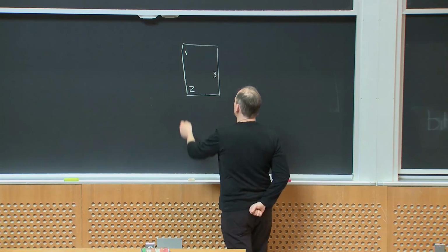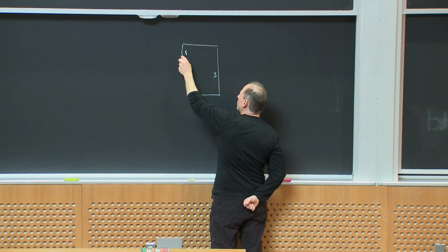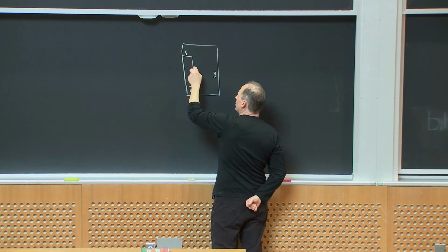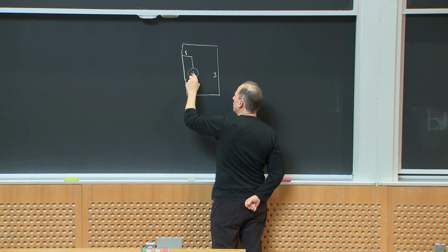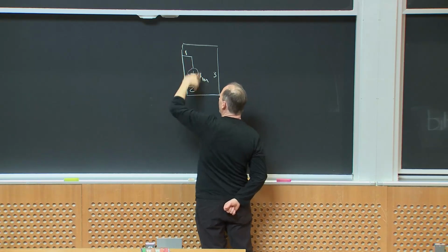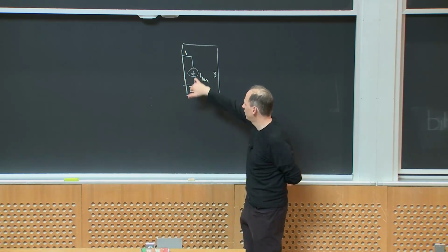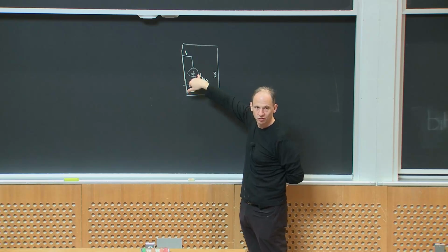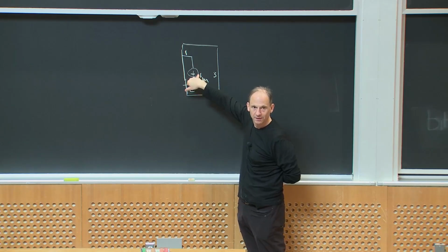So I might think of this coming in here and drawing a differential mode current, IDM, right? And that would include the power current plus any switching noise coming between these two terminals, okay?